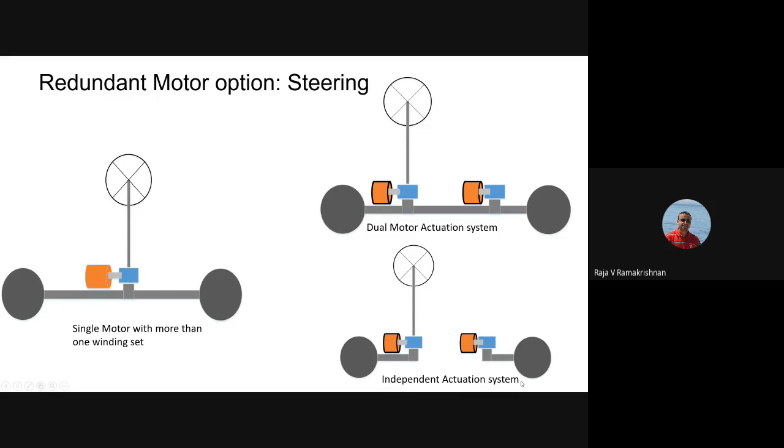This is where the new research is happening, where instead of having a traction drive, a big motor, to drive the vehicle, we want to bring the motor drive right to where the load is demanded. So think about doing motors directly at the wheels and the power electronics directly at the wheels. Then you automatically get different redundancy, because you will have four systems or two systems based on front wheel drive or all wheel drive. You can have four systems where you get multiple redundancy. This is where the newer research is happening, where the actuator is right where the demand is.